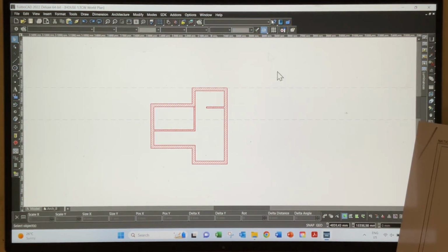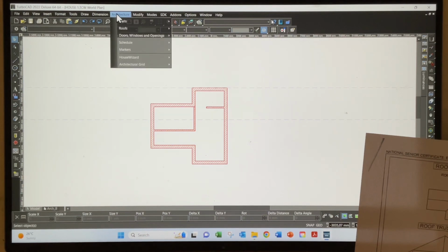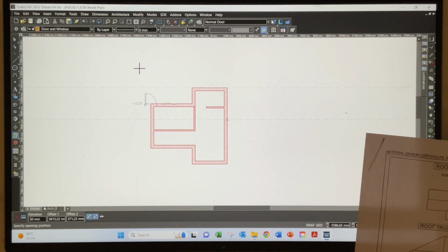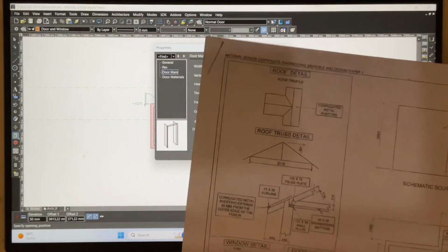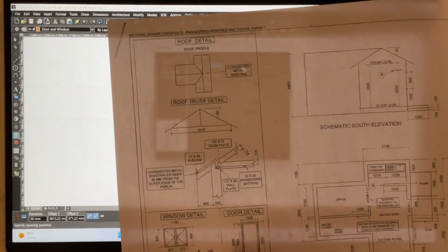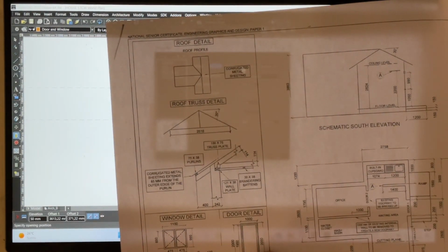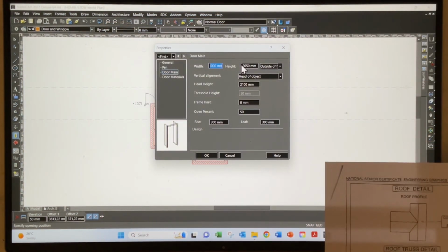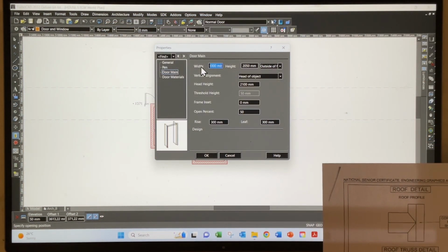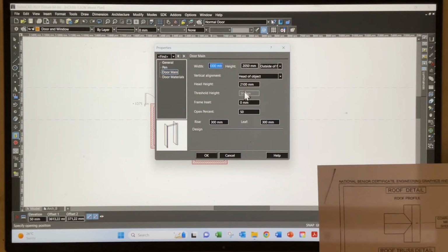You'll see over there that I've drawn a construction line on that external wall, and I've got an offset line of 2,500. Now I'm going to draw the door. I go to Architecture, I go to Doors, I go to Door over here. Right click the properties of that door, and you need to change the properties of the door to give me these dimensions over here, 2,050 and 1,000 in width. Okay, so it says height 2,050 and the width 1,000 over there.